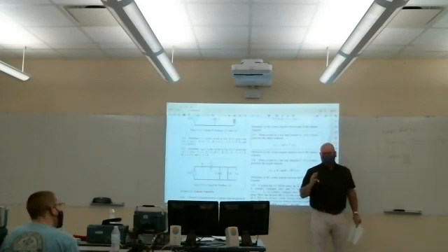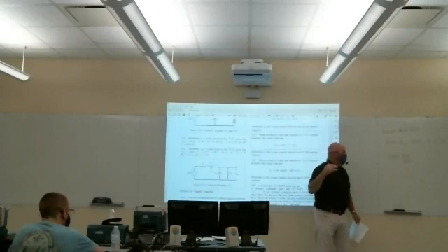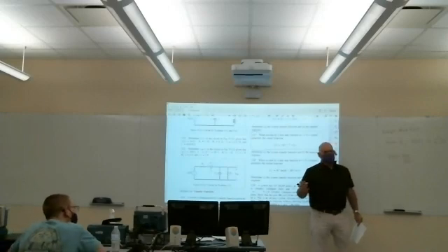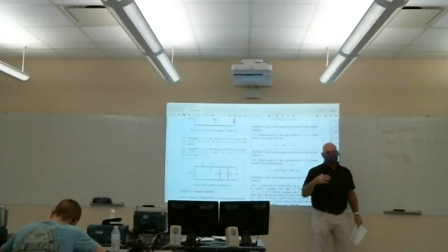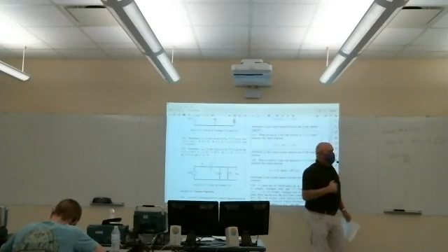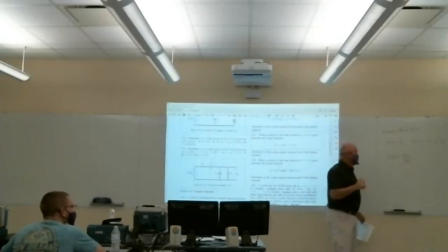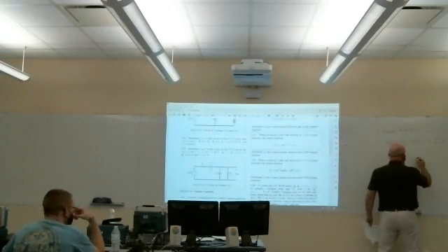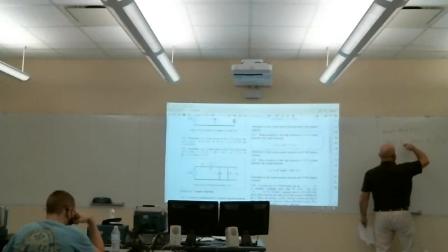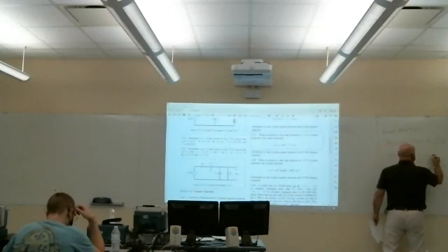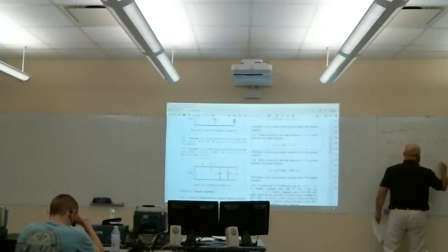It's a mistake I see a lot, but you find the output by multiplying h by x. The input times the transfer function gives you the output. So the transfer function is the output over the input. So in this case, flip that and multiply, I'm going to have 20s over s plus 3 cubed.